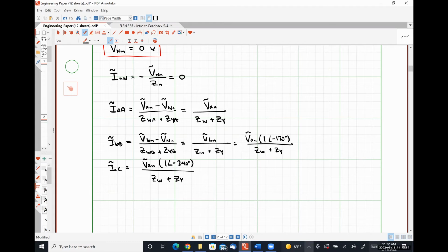It stems from the power industry saying something seems fishy along this street. What does that imbalance manifest as? Current in the neutral conductor. And does that mean there's some kind of loss of power transmission? No, there's just more power being absorbed on the system. So the utility is having to provide more power.